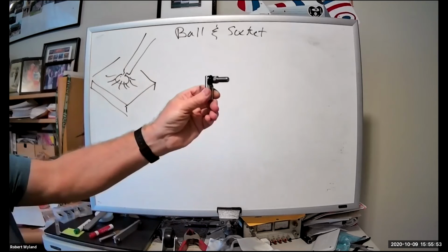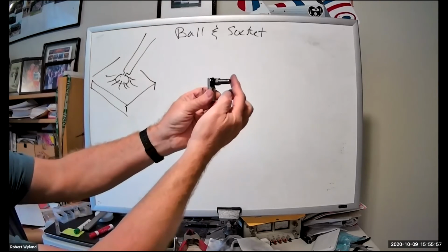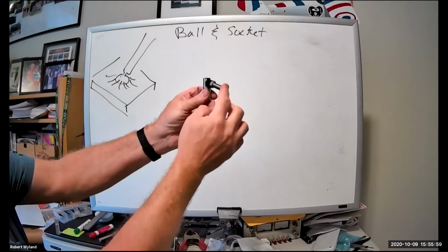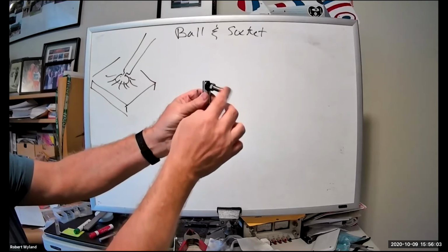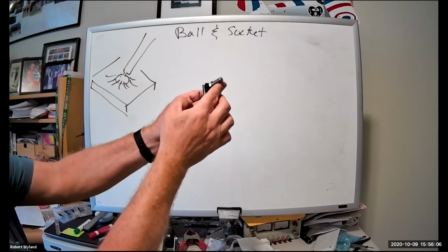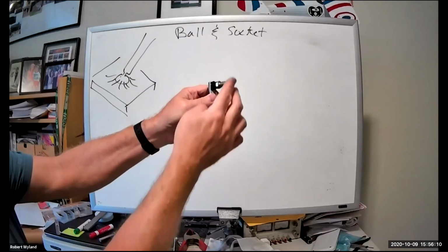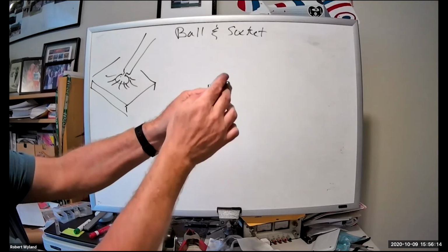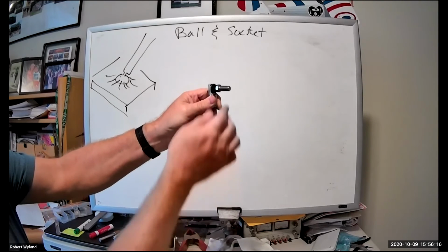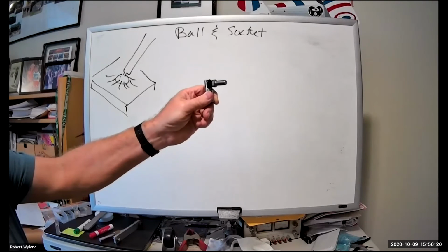If we look at Z, it would be coming out this way. So X, Y, Z. You can see that I can also rotate about Z. Not a lot. Now it does eventually hit the stops, and it would then no longer resist. But we're looking at the middle portion, and we're saying that no moment is translated through that range of motion. And that's how we design these things. We design these things to be in the middle of the range of motion, so we're not translating any moments.